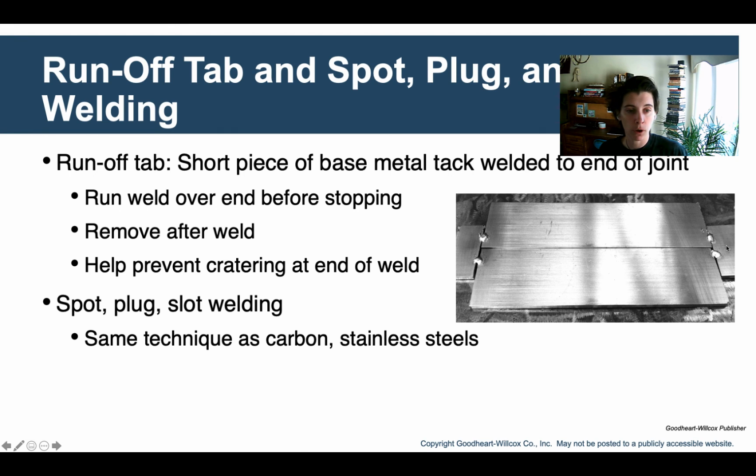You can also use runoff tabs, these short pieces at the ends of the weld, so that you start your weld here. If there are any problems, it's not on the main weld body, and you end it over here. So if you have any craters or weird stuff, again, it's not on the main weld. For slot plug or spot plug or slot welding, it's the same technique as carbon and stainless steels.